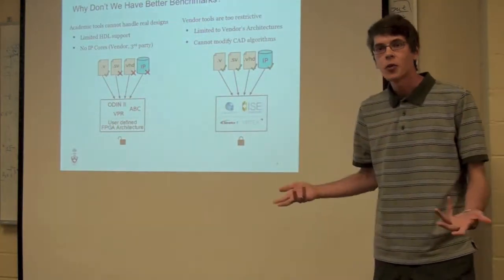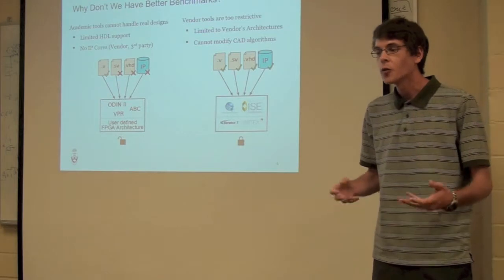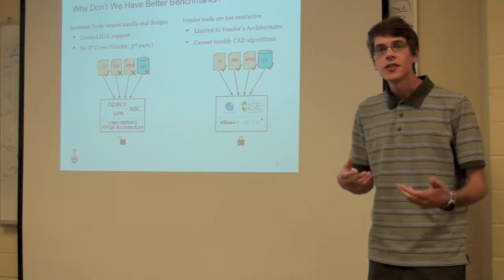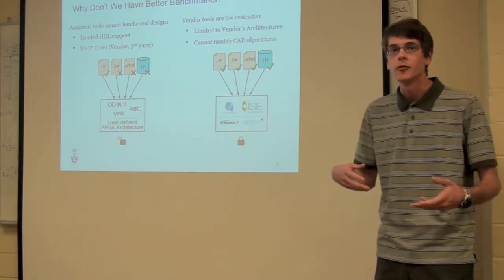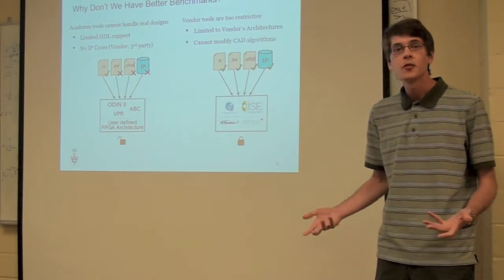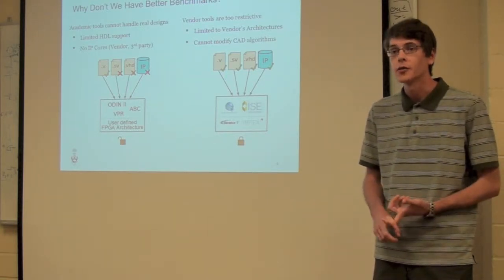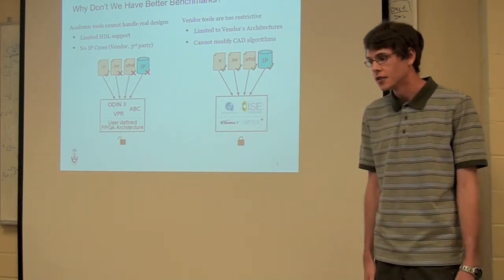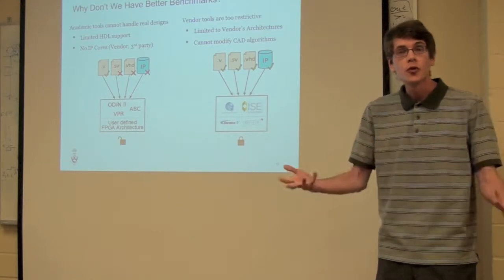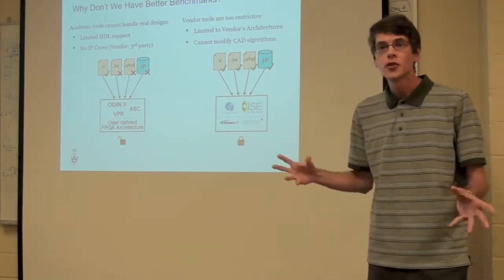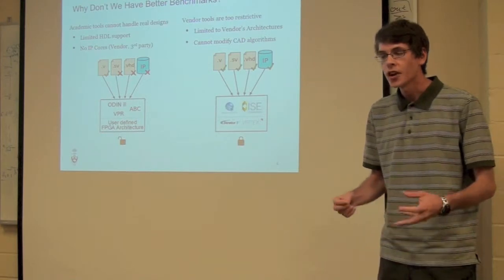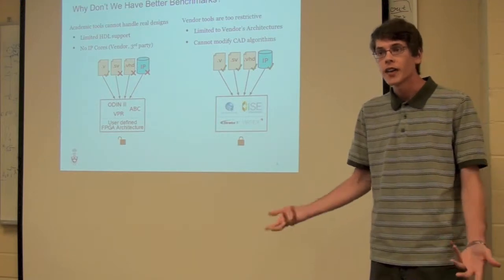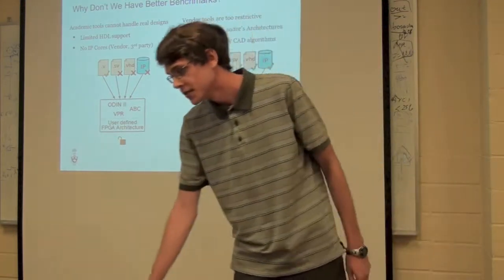So the question at this point is basically, why are we at this point? Why don't we have better benchmarks? And the reason is basically that the academic tools have been very poor at handling real-world designs. The academic tools typically have very limited hardware description language support, and they have no library of IP cores that many designs use. Now the vendor tools do support all of this. But they're really too restrictive for our research purposes. We're stuck targeting the FPGA vendors' specific architectures, and we can't go in and modify the CAD algorithms because all the tools are closed source.